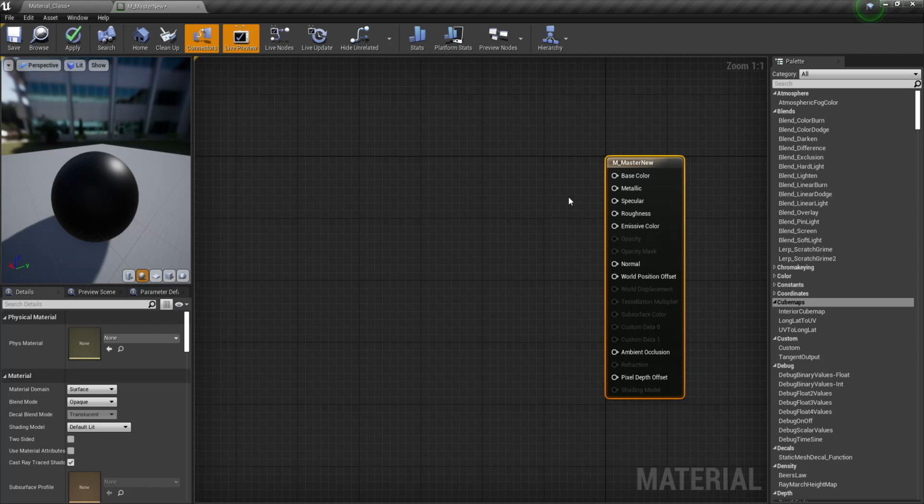So when we get something like this, definitely we will crank it up from 0 and pull it down from 1, right? But in most cases, metal is metal, and it is almost 0 or just slightly below 1. So it is almost black or white, right? Values like 0.4, 0.5, 0.6, most of the time we don't use in the PBR shading pipeline.